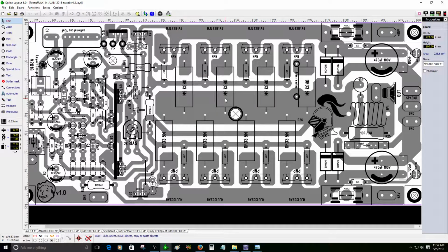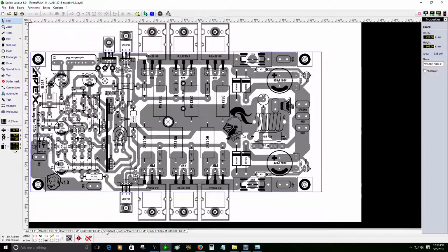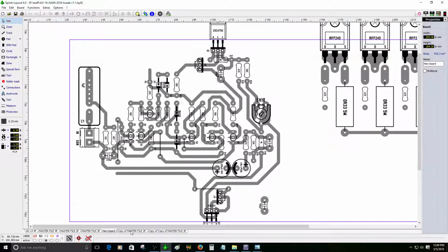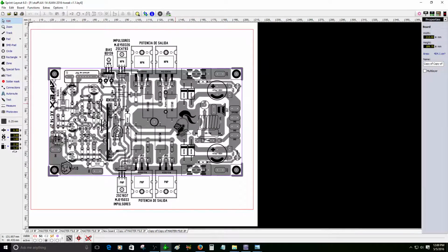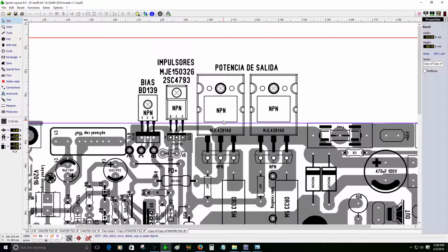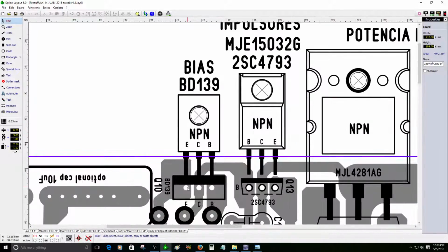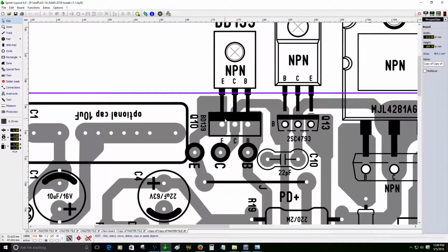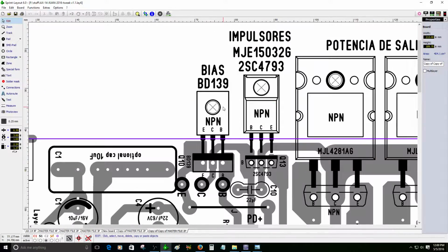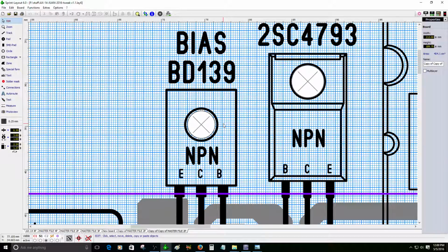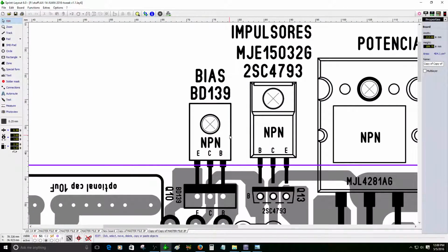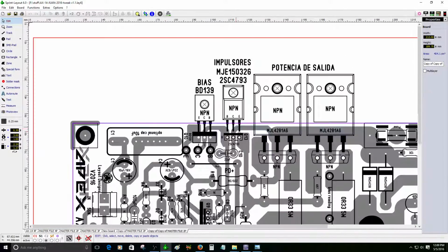As you can see, this is the 4-pair version. It's going to look like this after you put it into the heatsink. Make sure the Q10 is attached to the main heatsink. This is part of the bias adjustment. The transistor is really important to have on this circuit.